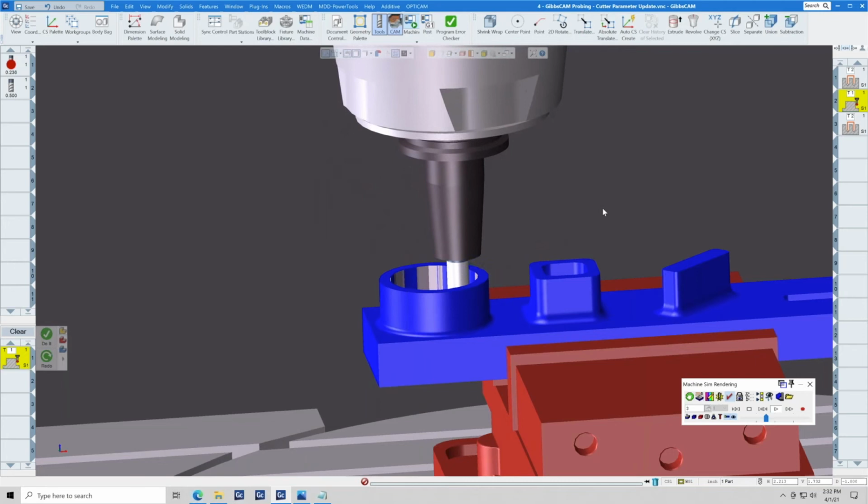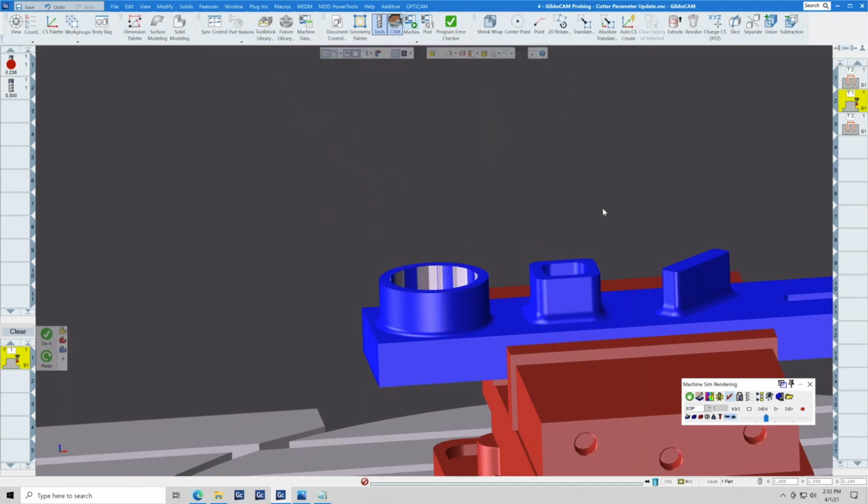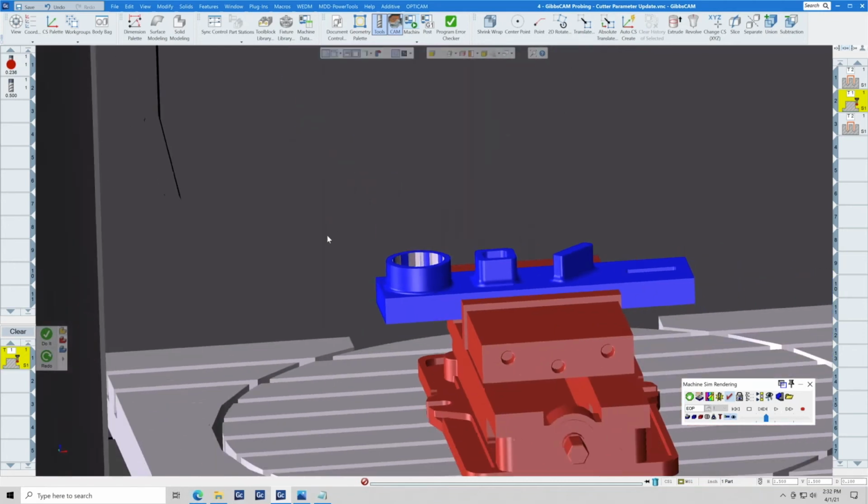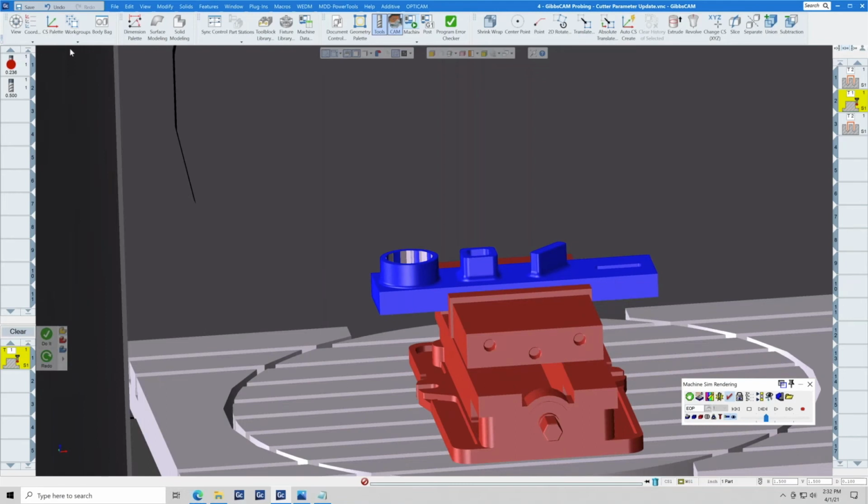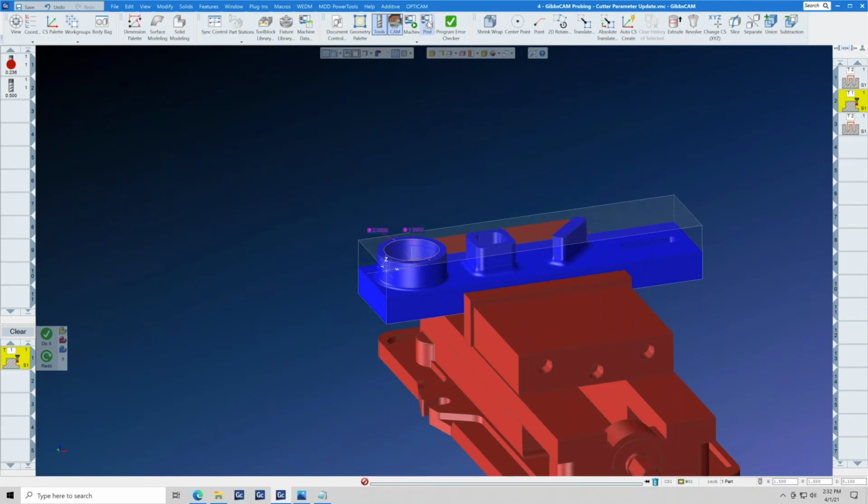Let's say that it was actually 4 thousandths. Then the probe would automatically update the wear comp for tool number 1 with that 1 thousandths deviation. And then in op 3, we go back and take the final finish pass.